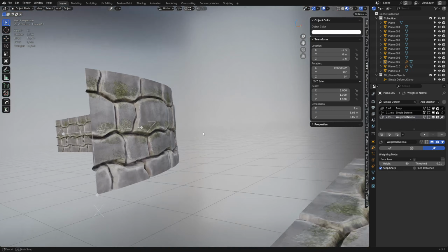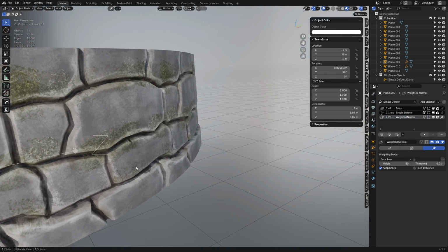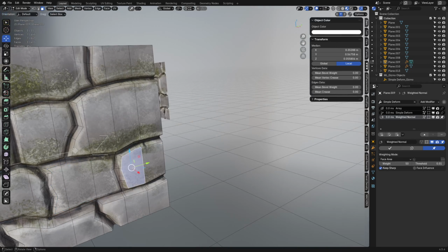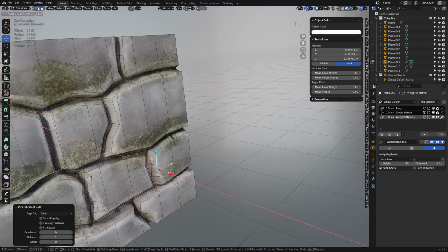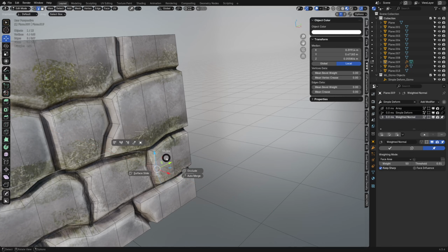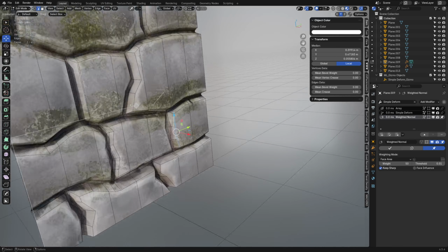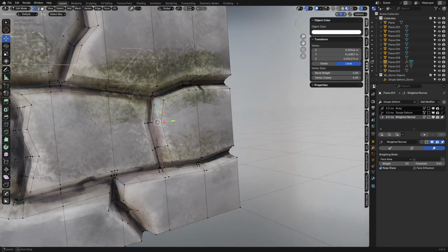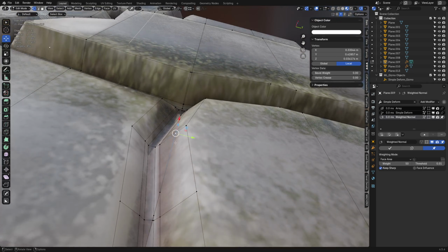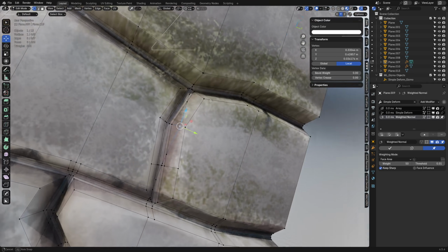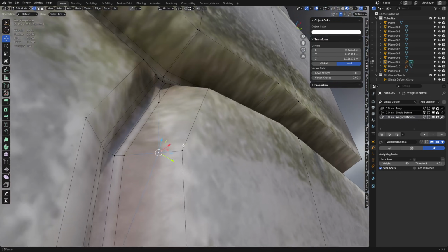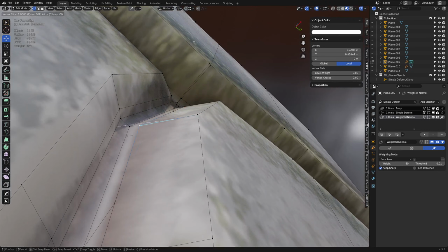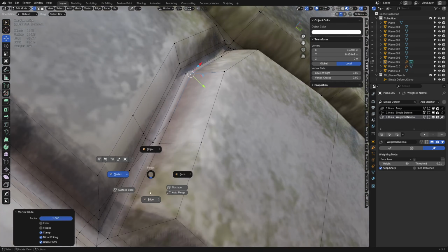A little bit more dynamic looking, perhaps. You'd also try just moving an edge, maybe. You can get away with it. You don't want to create non-planar faces, generally speaking. Like, well, it's okay to do it, but it can really make the shading look bad sometimes. So you got to be careful. Like this edge running across through here, it's probably better to clean that up too. You don't really need all that necessarily. So that's like the GG twice time.